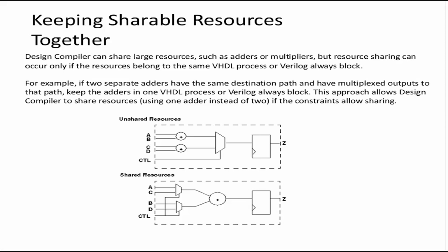Even if they belong to different always blocks, you can tell Design Compiler to do resource sharing, but that's again a separate set of commands. So to make Design Compiler work out of the box for you, it is best to do the resource sharing in the RTL itself by including them in the same always block.